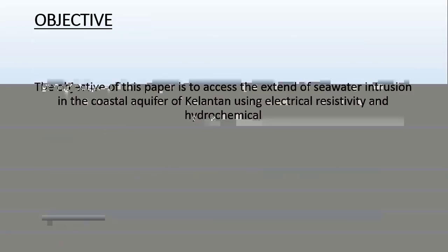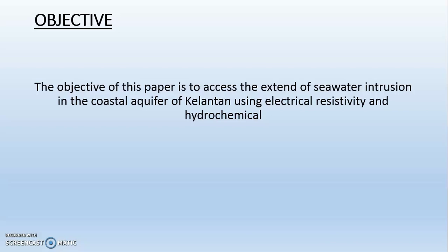There are several methods that can be adopted for studying salinization of groundwater or seawater intrusion. In this study, the objective is to assess the extent of seawater intrusion in the coastal aquifer in the northern part of Kelantan using electrical resistivity method and hydrochemical analysis.